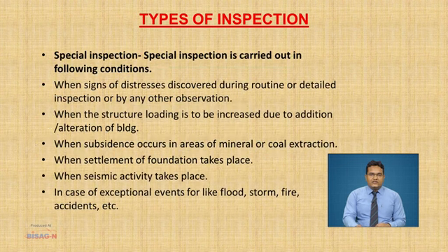Now, fourth is special inspection. Special inspection is carried out in the following conditions. First is when a sign of distress is discovered during routine or detailed inspection or by any other observation. Second is when the structure loading is to be increased due to addition or alteration of the building.